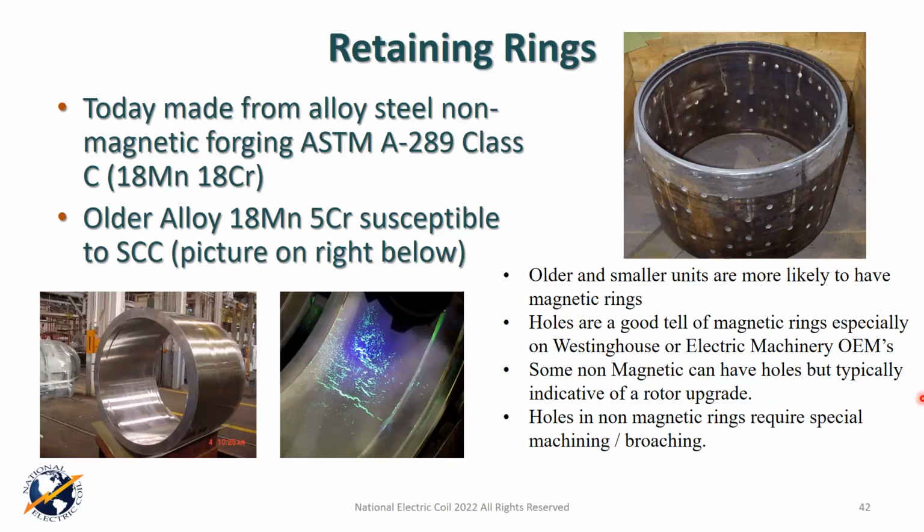Now, the question of risk of damaging other rotor components. If the unit has been properly maintained and is in reasonably good condition, that risk is pretty low if you use the right procedure. And today, the right procedure, we don't use rings of fire anymore, pretty much in the modern world anyway. We use induction heating.